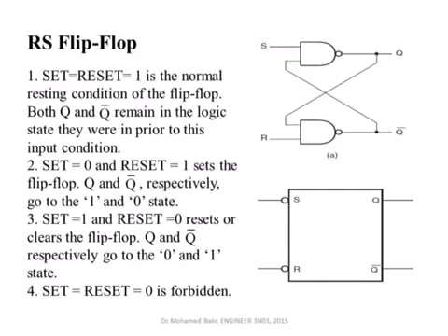The first flip-flop I'll talk about is called the RS flip-flop, and it is shown here. You can see it is simply two NAND gates, and we create some feedback from the output of the first NAND gate to the input of the second NAND gate, and from the output of the second NAND gate to the input of the first NAND gate. They call it RS flip-flop, meaning reset and set. R for reset and S for set. The one I'm showing you here is called an active low flip-flop, and you'll understand why this is the case in a second.